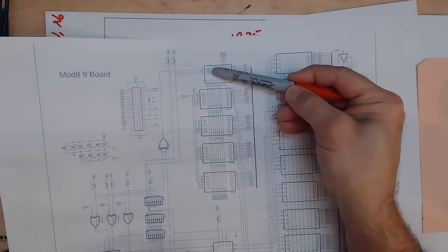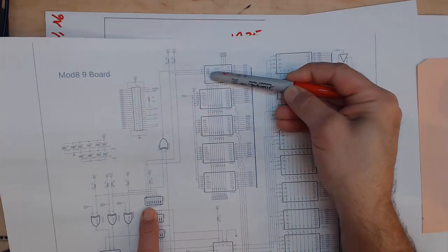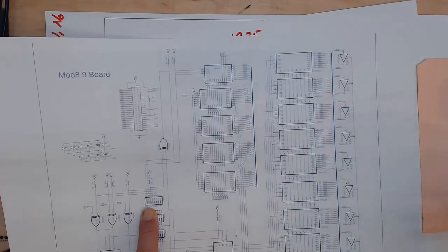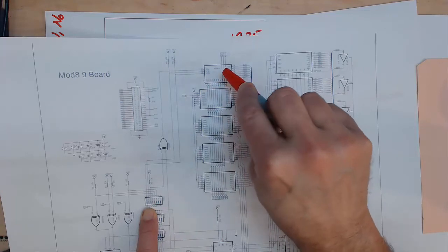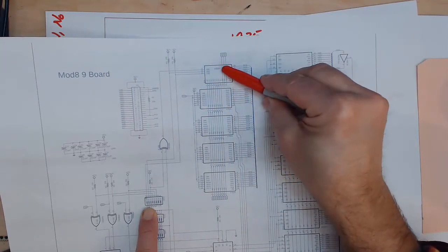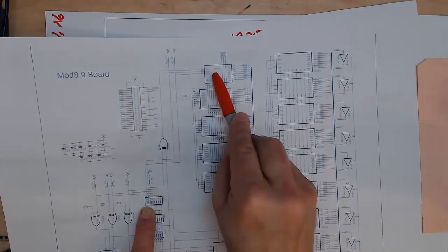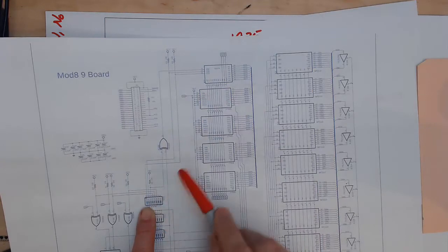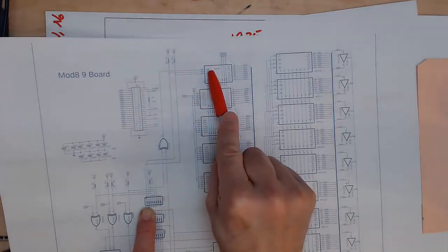So in this case, that's why we have to have a switch to determine what chip select 3 and chip select 2 need to be. So when we get this chip, we put it in, we look at the number on the top. If the number on the top is a 6, that meant that 2 and 3 both had to be 1. So we had to set these switches so that 2 and 3 would be 1 to enable that chip. So we would set switch 1 and switch 2 open, so these pull-ups would then pull them to 1.